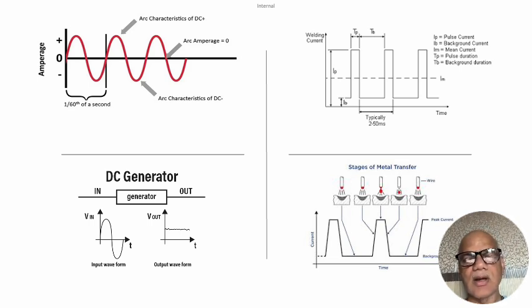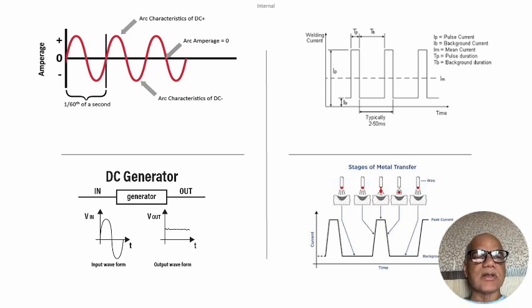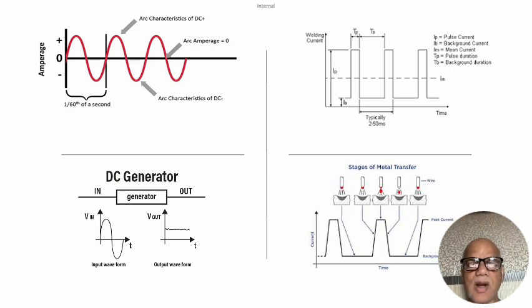But now with the electronic controls, this frequency can be increased, and many times it is very helpful. Instead of one pulse getting completed, or a rectified wave getting completed, in 1/50th of a second, you can make it 2 kilohertz, 5 kilohertz, 10 kilohertz, whatever frequency your rectification can take through electronic control that is nowadays available, and that helps in really stabilizing and making ripple factors almost zero.